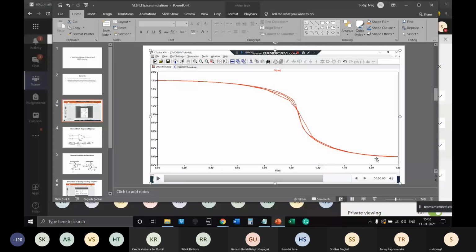So between 0.4 and 1.5, this is the noise margin that you can consider. This is an undefined region, or you can say that this region is not allowed for an inverter to operate. So you should make quick transitions. For that to happen, if you remember the transient waveform, there is a finite rise time and fall time. Ideally we need rise time equal to 0, fall time equal to 0. Practically, definitely there are limitations.